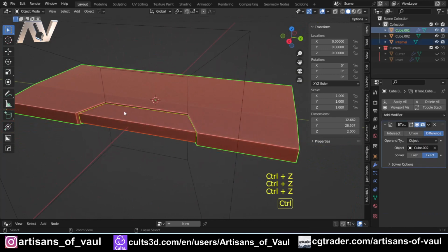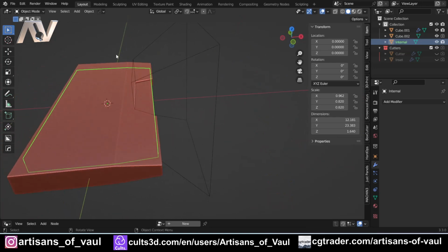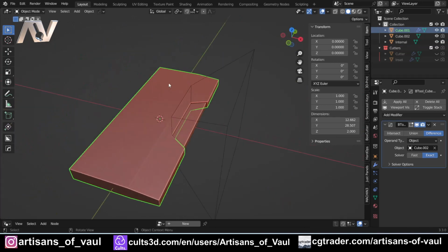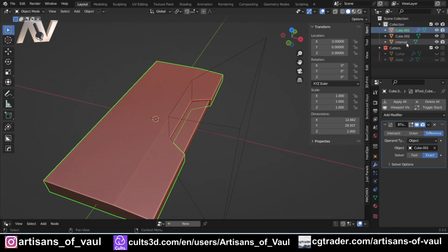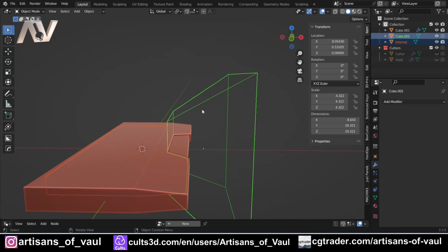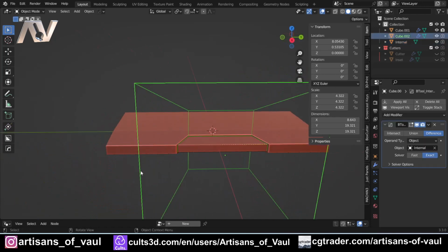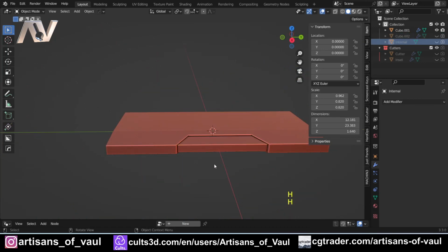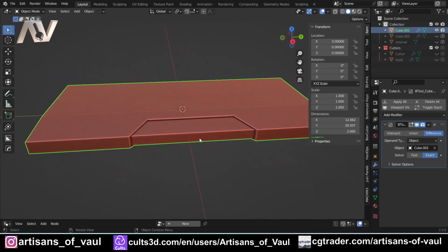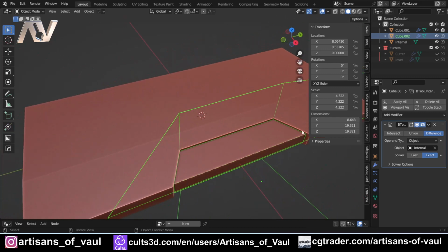Now I would say just a first pro tip, to save yourself some time, don't add this to this cube, because you're probably going to make some problems at some point. This would be fine, but it's going to get a little bit complicated later on. So actually you're much better instead taking this, shift selecting your cutter and pressing Control and minus and cutting it out of that. And what that allows you to do is now we just need to H to hide this and H to hide this, and it's working. And you'll generally find this causes less problems. So that's my first pro tip. Generally cut the cutter, don't add it to the object that you're trying to add this inset to.